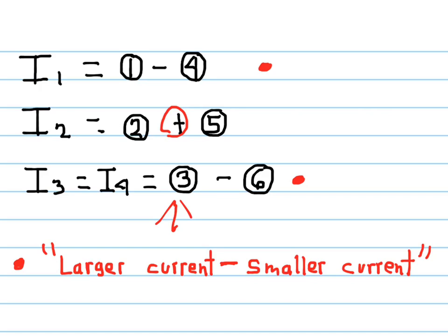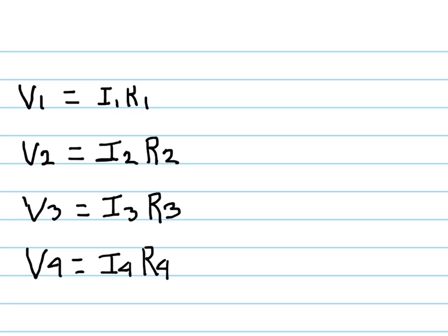Once you record all the final currents and work them out, you need to calculate the net voltages. This would be the voltage you'd measure if you built the circuit and took your meter. Using Ohm's law, it's simply the resistor current times the resistance, and away you go. And if you desire or need to, you can easily calculate the power dissipation through each resistor by using any of the standard formulas.